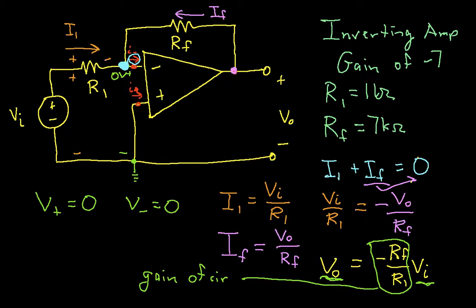So that's pretty much all there is to doing this design. Now, one question you might have is, how do we actually choose a value of R1, since once we choose R1, then RF will be specified? We typically do that by looking at the typical ranges of the input voltage, looking at the specifications of our op-amp to see how much current it can source, and looking at how much current we're willing to let flow back through RF, because that's a power drain, and so on.